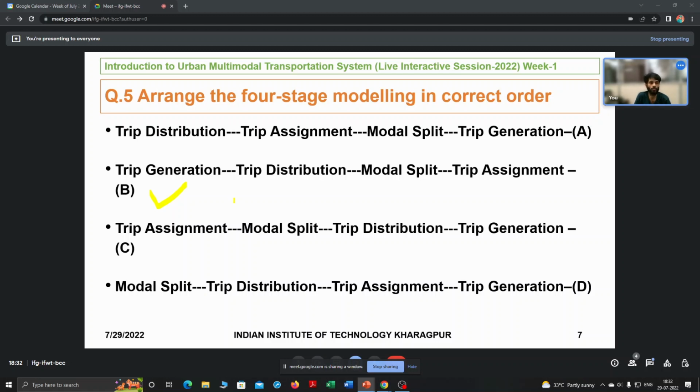What route will they use, right? There is a model in transportation modeling called the all-or-nothing assignment model. In that model, you find the shortest route based on not only travel distance but maybe also travel time, because those may not be the same. So that's how it starts from trip generation and ends in route assignment, or trip assignment.